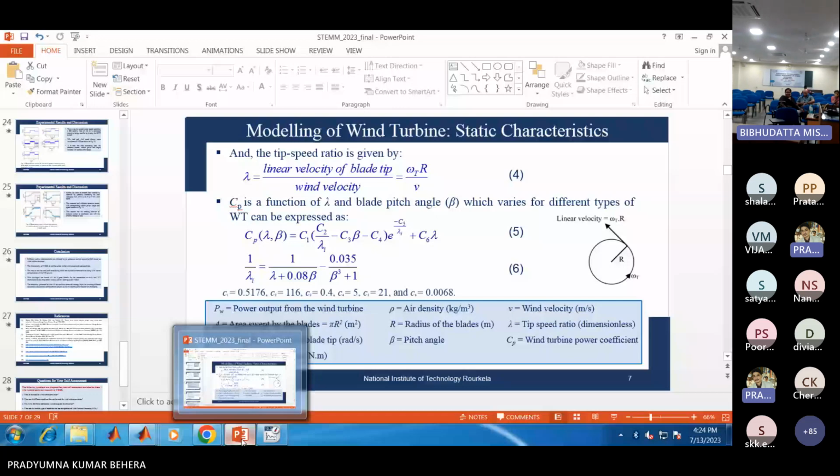It will generate a reference current. Basically, in the case of a DC to DC converter, this reference current is for comparison with the inductor current of the converter. That current will be compared with the actual inductor current and again processed through a PI controller. So it will generate the duty cycle for the converter. So you are asking why it is generating current, not duty? That is the question, right?